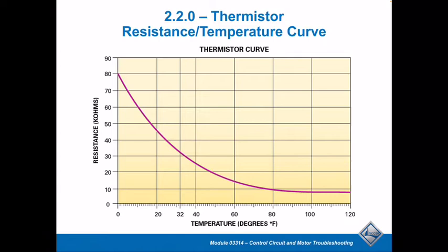2.2 talks about thermistors, and that's what I want to focus on. Most of our units nowadays have a thermistor. Electronic thermostats all have thermistors in there. This is an important part: thermistors have a curve. They give us a certain rate, and sometimes I'll see this in table form, sometimes in a graph like you're seeing here. What they identify is the temperature versus the resistance of this device in thousands of ohms, so they're calling it K ohms, basically kilo ohms.